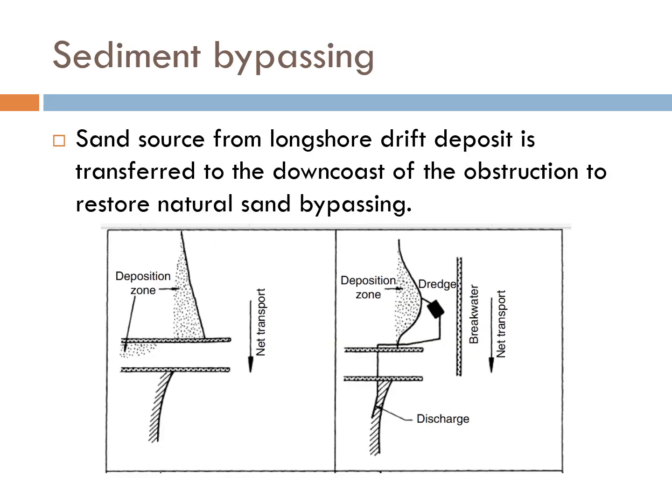Since the jetties interrupt the longshore transport, it may result in long-term accretion on the updrift side and long-term erosion on the downdrift side, which is undesirable. As a result, a solution for sediment bypassing must be provided, in which the idea is to transfer the sand from the updrift side to the downstream side so that it maintains or restores the natural sand bypassing without going into the waterway in the coastal inlet.